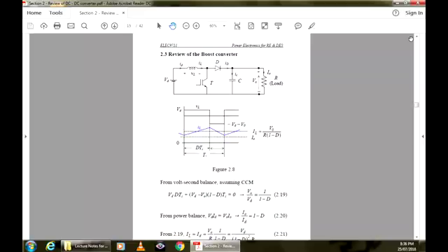Current will rise like that. Let's say it starts from a non-zero positive value, and then it will rise to a maximum. And then when you switch it off, what happens then? The current that was in the inductor will then flow in this circuit. This switch is off, so the inductor current I max will start to flow here. Some of it will go here, some to the load.